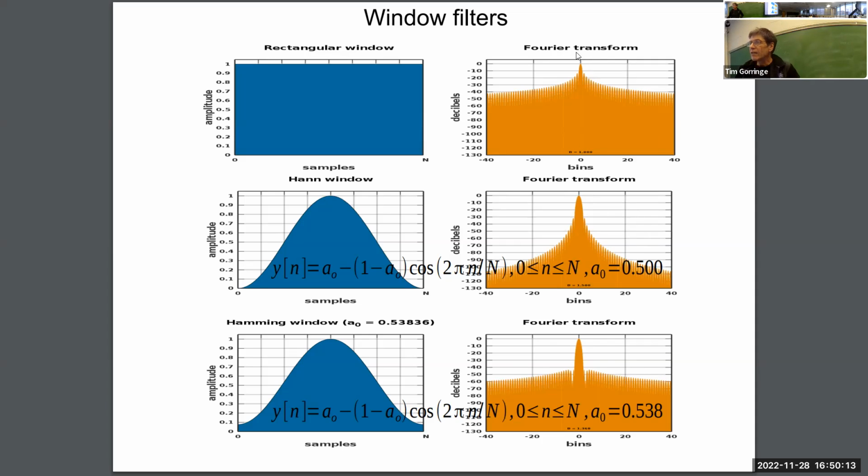In the very center, at 0, this would be a very low frequency, and so it is unattenuated by any of these filters. Very low frequencies get through all of these filters. As you go away from 0 towards the left or the right on any of these plots, this vertical axis, these negative decibels, is increasing attenuation of those frequencies by these filters.